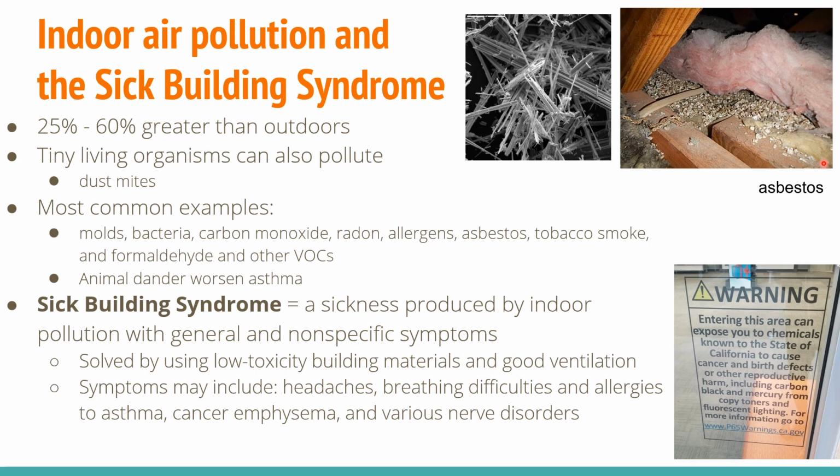With all these air pollutants, it can lead to something called sick building syndrome. Sick building syndrome is a sickness that's produced by indoor pollution with general and non-specific symptoms. It's solved by using low toxicity building materials, so instead of asbestos in insulation, we use something else. And also with good ventilation, because if we have good airflow, then all those pollutants are not trapped within the building that you're staying in, kind of like the thermal inversion. Symptoms of sick building syndrome can include headaches, breathing difficulties, allergies, asthma, cancer, emphysema,